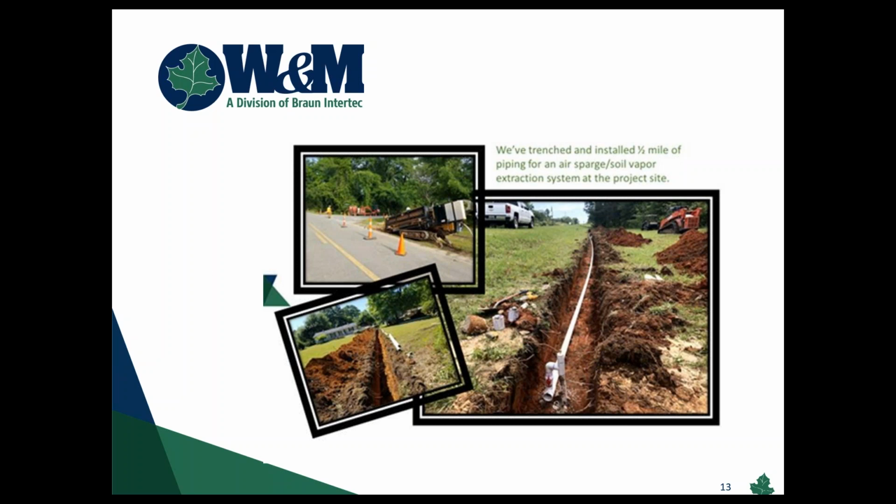And what's not pictured here, just off site from that well, is a series of soil vapor extraction wells that are set above the groundwater contamination, slightly in it, that'll use vacuum to pull nearby soil vapor out, plus the stripped air from this, and send it off to treatment. So this is a pretty amazing site that's got a huge gallery of both air sparge and SVE wells, and it was a great candidate and a great technology selection for the site's needs.